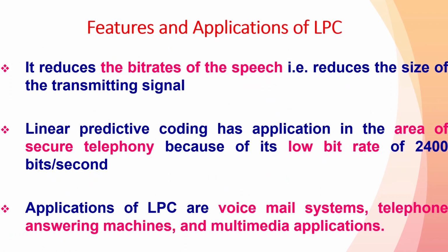Next, key features and applications of LPC. Coming to the features of LPC, it reduces the bit rate of the speech. So efficient representation will be possible for speech using LPC. It reduces the size of the transmitting signal. And by using LPC, we can achieve a low bit rate of 2400 bits per second.